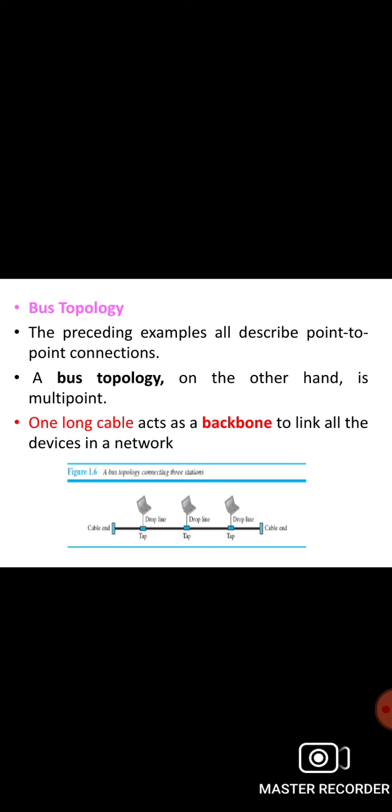Disadvantages include difficult reconnection and fault isolation. A bus is usually designed to be optimally efficient at installation. It can therefore be difficult to add new devices. Signal reflection at the taps can cause degradation in quality. This degradation can be controlled by limiting the number and spacing of the devices connected to a given length of the cable. Adding new devices may therefore require modification or replacement of the backbone.